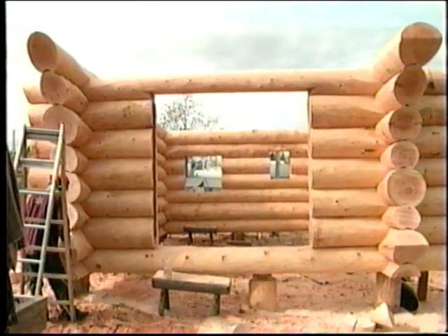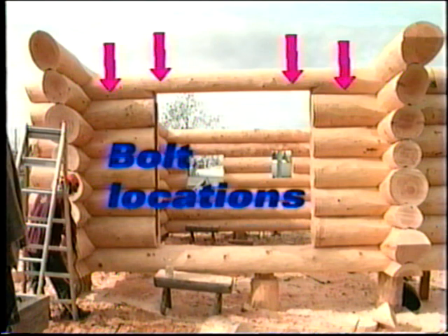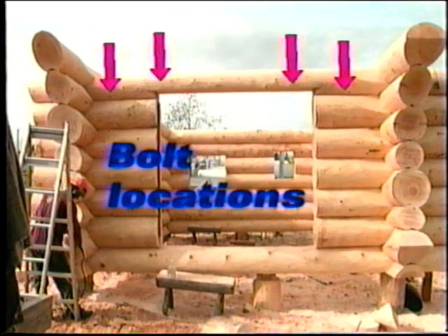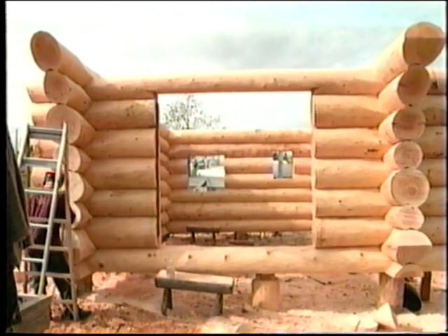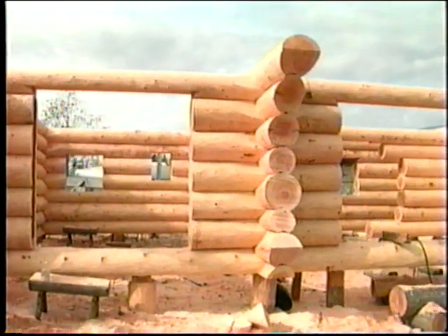There are usually enough window and door locations along with the through bolts at the corners to meet the standard requirement of 1 fastening every 2 meters, so use these as much as possible.